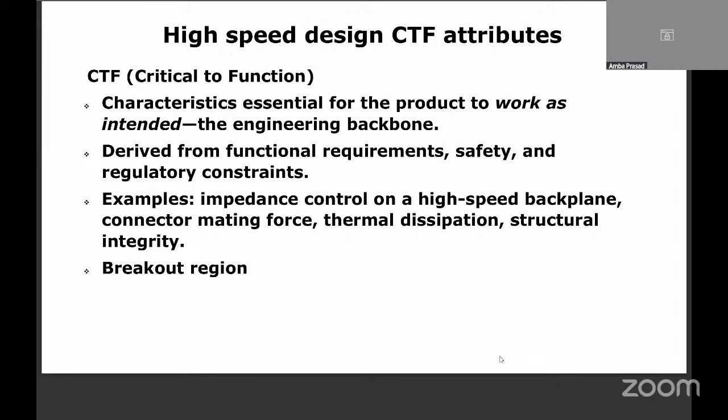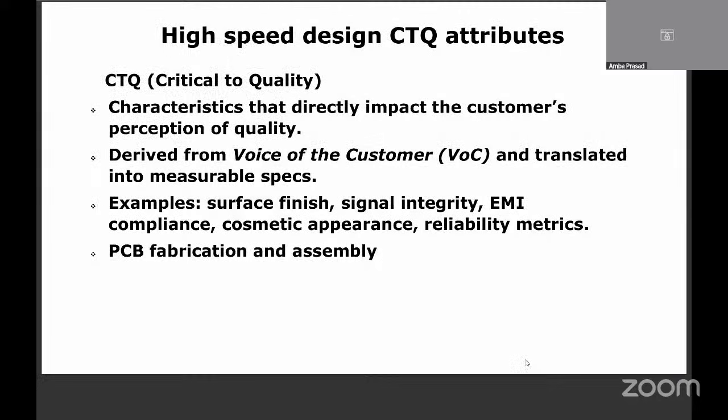So that's it. Then impedance control on a high-speed backplane, connector mating force, thermal dissipation, via structural integrity are very, very important. And breakout region. This breakout region itself, I can have one session, and there is so much to talk about that. Maybe we can do it a little later, sometime. Let's go to the next slide. I think this is it now.